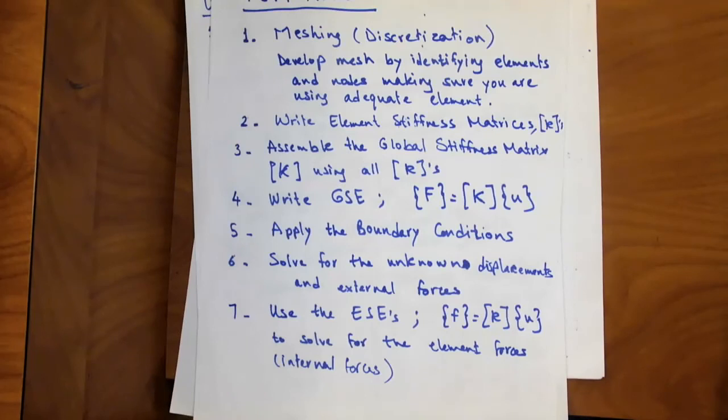The beauty of the finite element method is that I do not have to worry about drawing free body diagrams or coming up with compatibility equations. I just have to discretize. It's very well suited for a computer program to break it down, write the element stiffness matrices, assemble the global stiffness matrix, apply the boundary conditions, solve for the unknowns, and use the element stiffness equations to find the internal forces. You got it all.